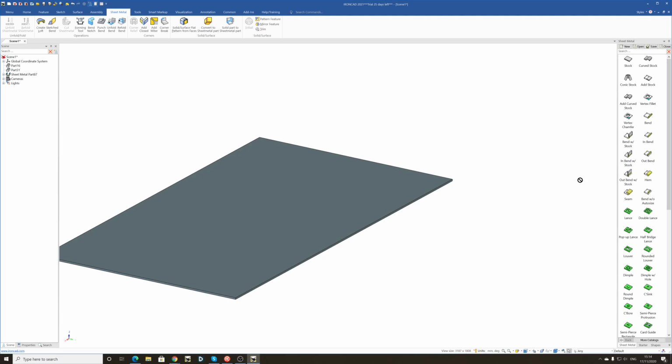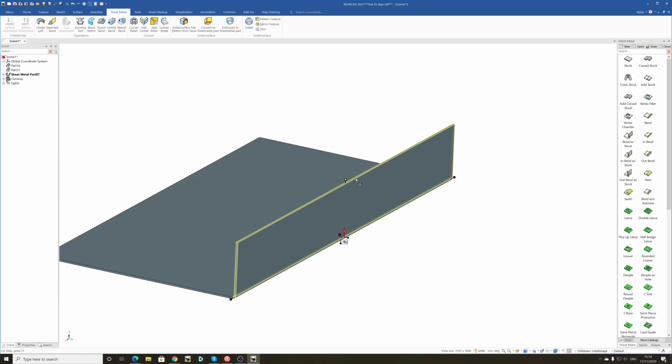So let's just drop an in bend in, put it on that corner. And I can just drag and drop, similar to all the features within HiCAD with the IntelliFeature. I can change the angles, the sizes and everything I want to do that. Radius size of the bend. I can move it partially in, out. You know, you have loads and loads of options. I can double click on that, and then I have the choice of depending how I want to measure the size. So if I pick this one, I want that one to be 100. Done.